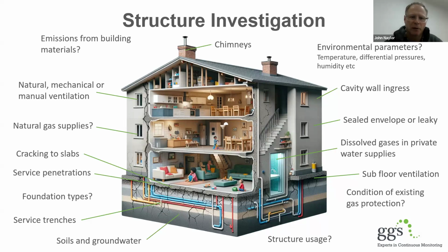Another point on there as well, I've got cavity wall ingress. That's something that not many people actually go look for. But it's definitely a pathway and a route for ground gas to come in up through the foundations and find itself sometimes in higher levels where it's completely bypassed the ground floor and it's up in the loft. Again, how do we go and investigate those kinds of features? Okay, so lots of different things to go look at when we look at the structure. So that's one of the main investigation techniques, is going and having a right good look at what's going on.